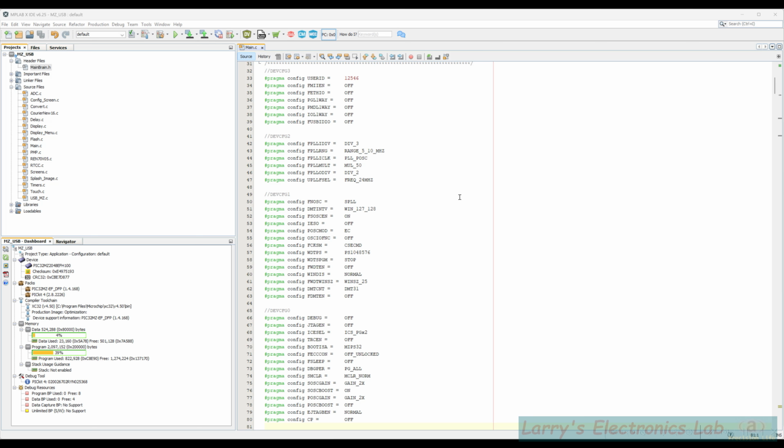That's so that if you don't use the module, you have the default IO available. But if you want to use the module, then you have to lose a few pins off your IO to utilize that module. So with this IOL1WAY register on, when you do your initial configuration, your programming, your firmware cannot change any of those pins on the fly. But if it's off, then your firmware can change the pins and reconfigure stuff while it's running, in runtime.